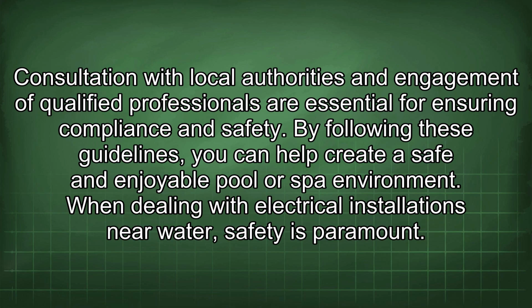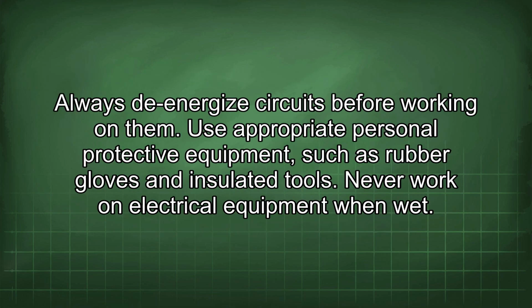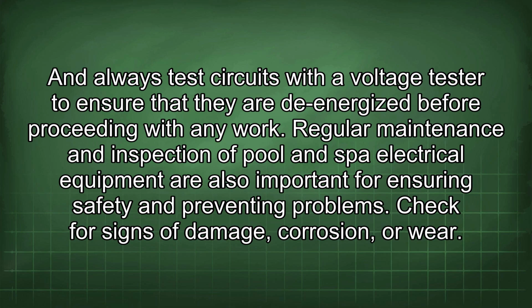When dealing with electrical installations near water, safety is paramount. Always de-energize circuits before working on them. Use appropriate personal protective equipment, such as rubber gloves and insulated tools. Never work on electrical equipment when wet. And always test circuits with a voltage tester to ensure that they are de-energized before proceeding with any work.